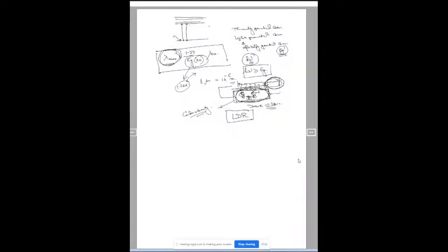And if the intensity of the light is changed, more carrier generation will be there. So from this LDR you can find out not only the presence of light, but also the intensity of the light, because the number of carriers generated is directly related to the intensity of the light. So this is a very simple example where a bulk semiconductor material can be used to sense light. Right? These are called photoconductors.